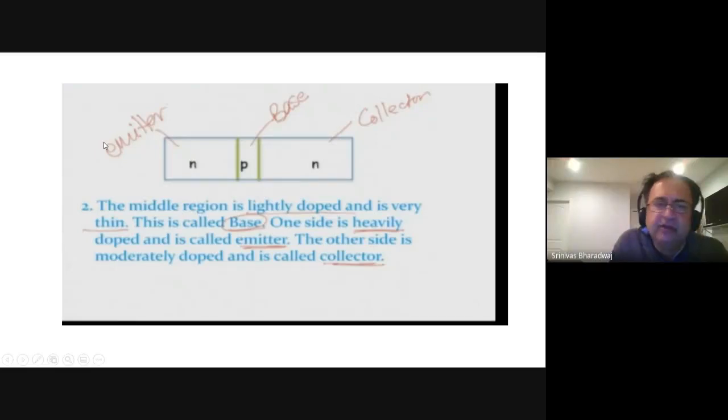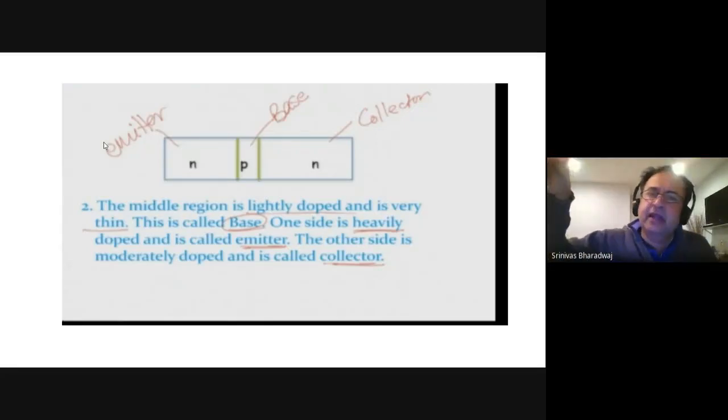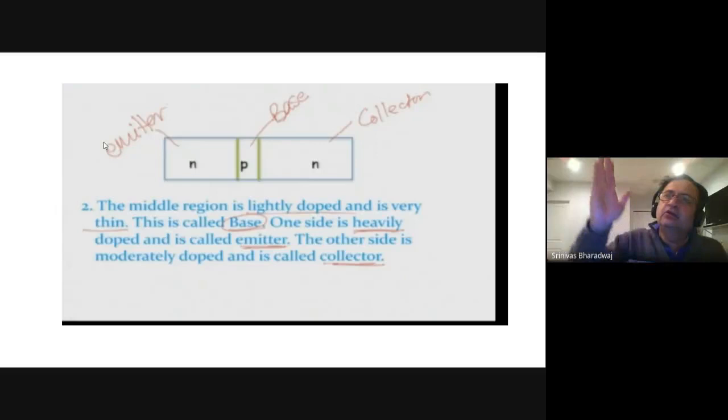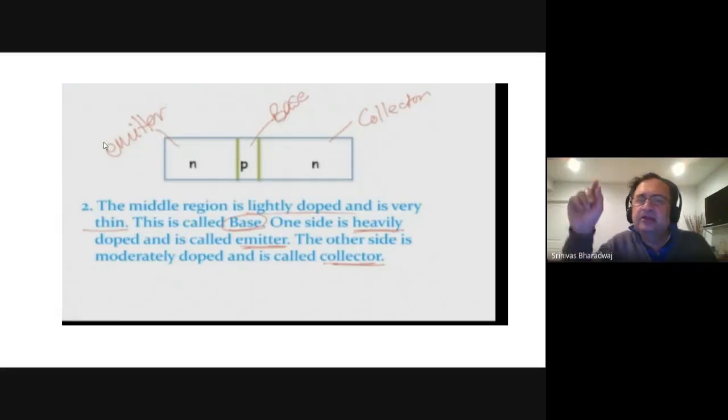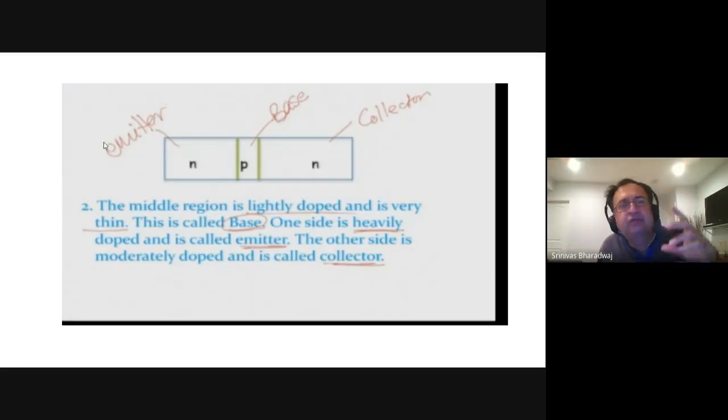That voltage is used to push the operating point of the transistor to the part where it is somewhat linear. When you apply an additional voltage there, you will have a corresponding increase in the current, which is linear.